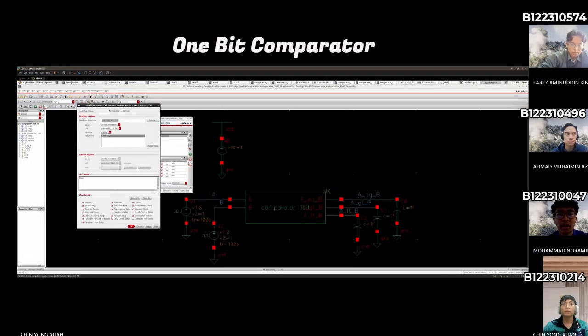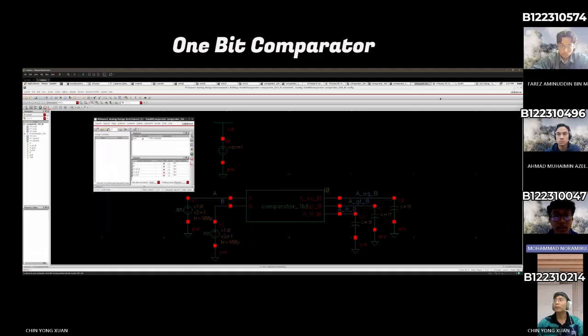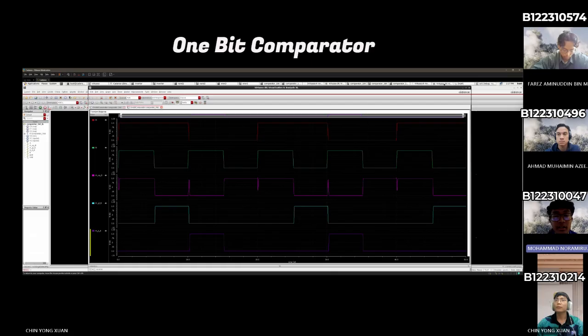Thank you, Faris. My name is Muhammad Ibrahim. For our physical design work, we ran a post-layout simulation using the extracted view. Looking at the result, the core logic still holds true perfectly across all four input states. But if you look closely at the output transition, you can see this tiny voltage spike or logic glitch. Furthermore, the edges are slightly rounded compared to our pre-layout simulation. This is the physical proof of the RC propagation delay caused by the wire routing we just showed you.